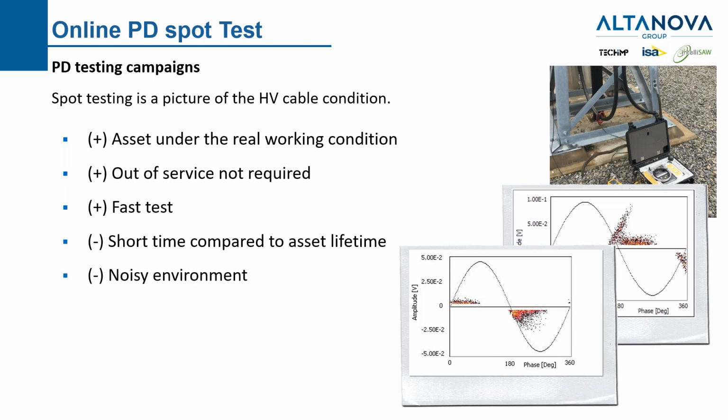And we also have a noisy environment. Why can the noisy environment be tough? Because it's easy to misunderstand PD signals. It's easy to mistake an external surface discharge on the termination connection for a discharge. So we need some skills to make the analysis, some experience on that.